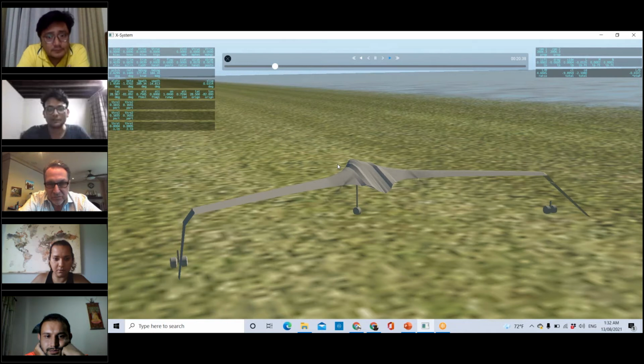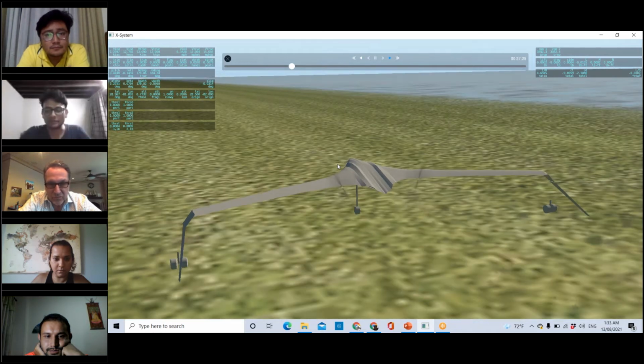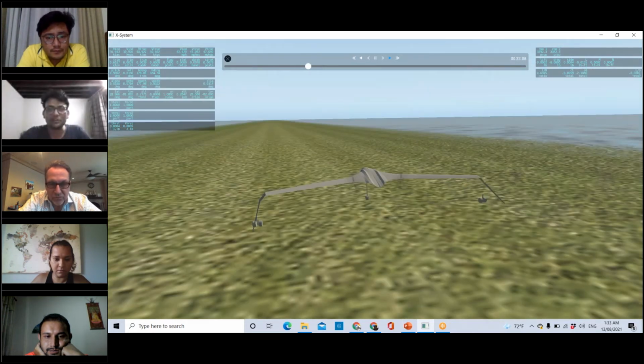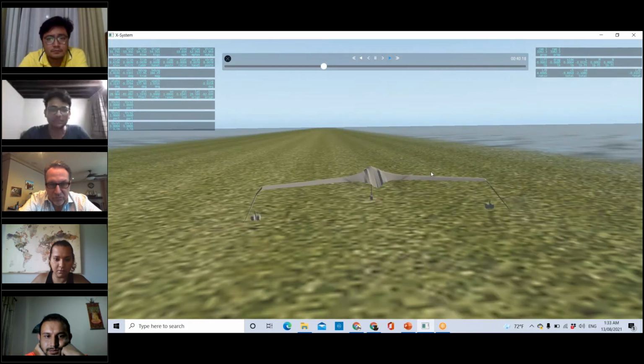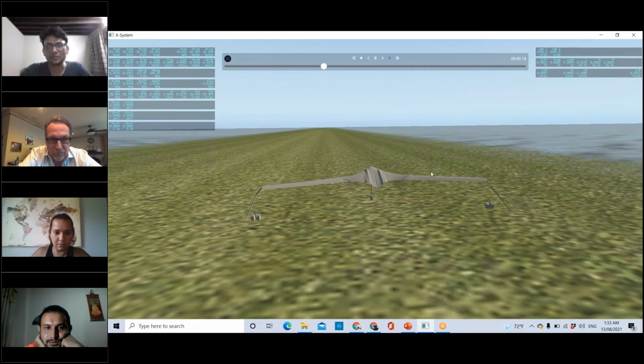So it's very steady on the ground. That's partly to do with how we put the landing gear as well. And then I trim the elevons to about 0.6, and then the aircraft flies at about 52 knots. And then I do some tests of maneuvers shortly.